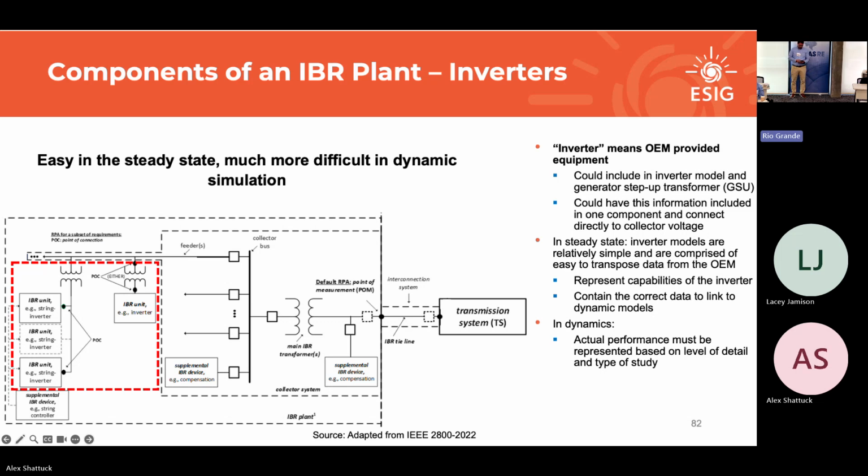For the dynamic piece of the EMT, this is where we talk about all the parameters you have to test and tune at the inverter level. The little nuance here is that the vast majority of the testing and tuning that end users do, and I say most end users, not like the Lucases of the world who are doing really highly specialized studies all of the time, you don't do a lot of tuning at the IBR level. You may be changing ride-through gains, but a lot of the other parameters at the inverter level are things like capability parameters and current limits and recovery parameters, which are the vast majority of the time better done with the OEM's guidance.